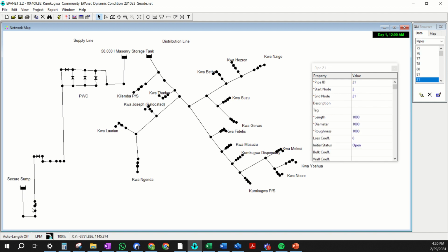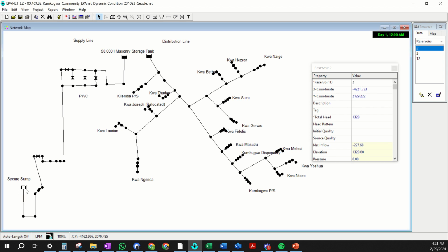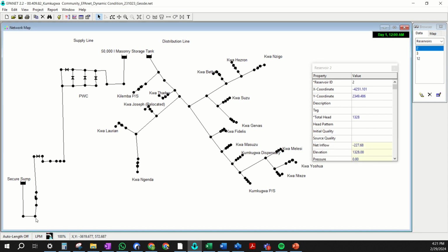This sump is modeled like a borehole, but it's not quite like a borehole. The way I would adjust this, I would only have one pipeline between the sump and the pump. Actually, never mind. You can do it like this, because this model allows you to show the water level in the sump right here, the bottom of the sump using these 2 nodes, and the pump depth of installation using these 2 nodes. So that's good.